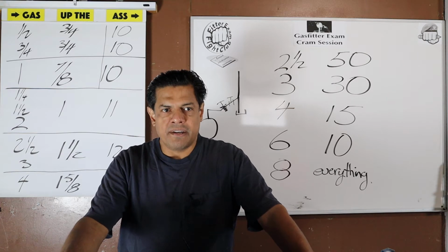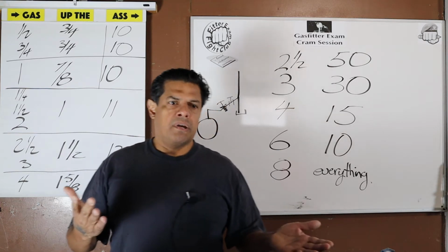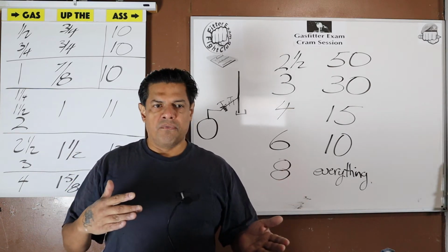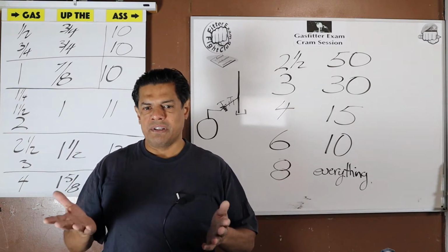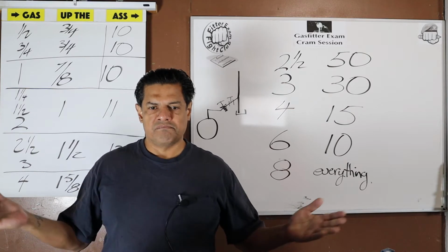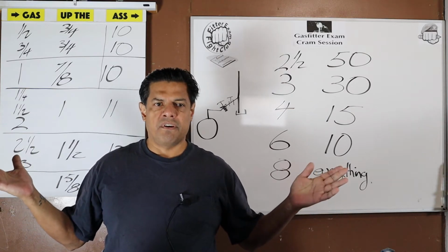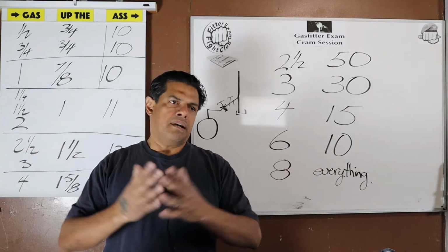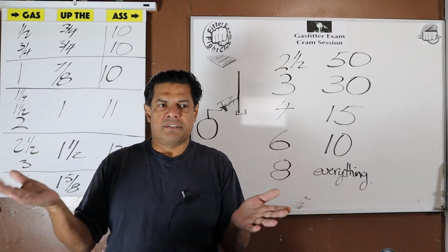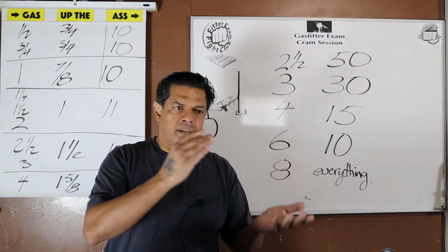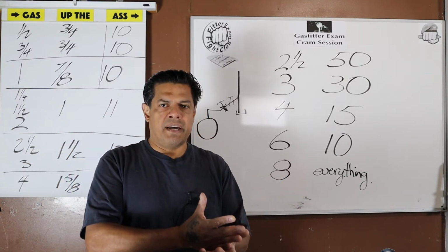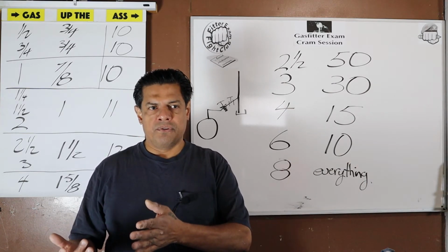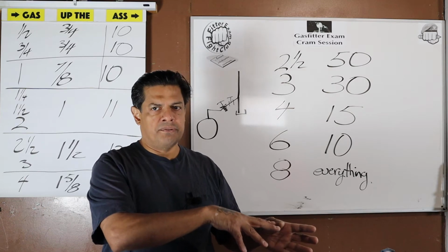So if we're running cooking gas to an apartment building, if each unit has one stove, and each stove, we're going to say, has a certain requirement. Let's say, for the sake of argument, each stove needs a cubic foot of gas to work, right? And we have 10 units, 10 stoves, so that's 10 cubic feet of gas. We use that number to determine now the size of the piping according to the utilities, tables, and charts, etc.